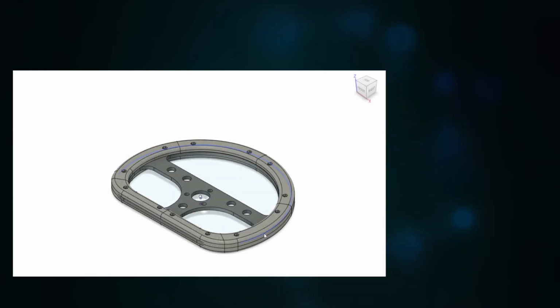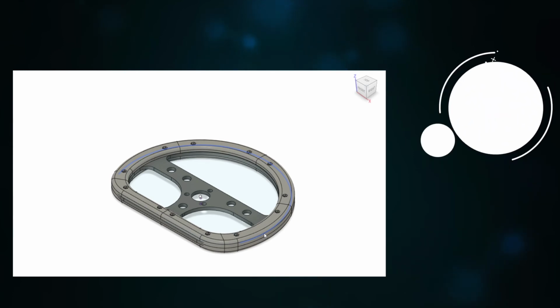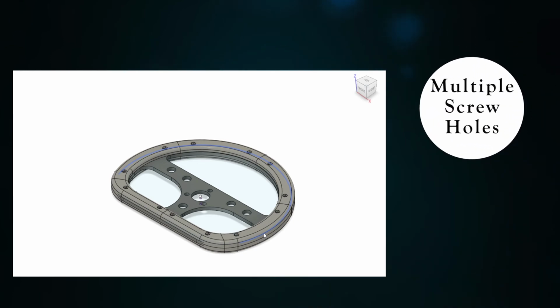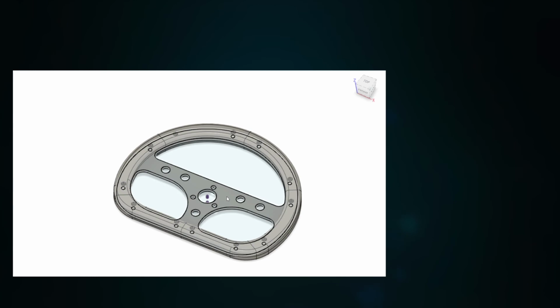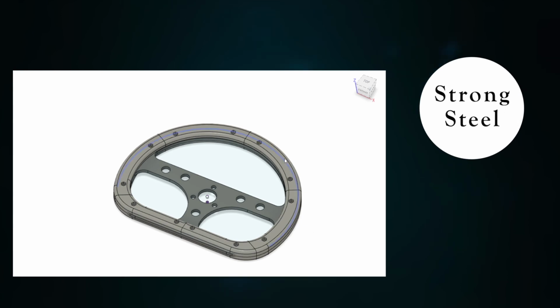The grip is split up into multiple pieces so that the parts can be easy to manufacture and that they're also customizable. I calculated the stress on the center to figure out which material was the best for the rigid part of the steering wheel, which is right here. We decided to use 6.3mm mild steel to be the rigid part.